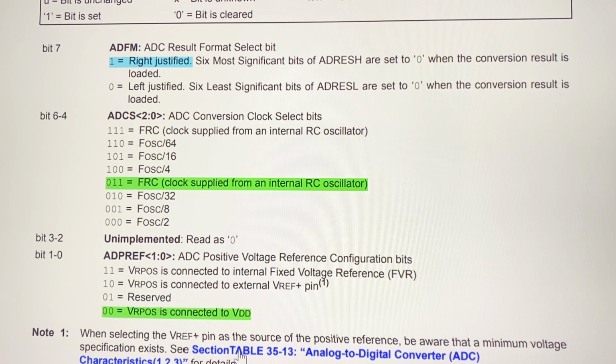But if you are working in an instrumentation experiment, and your sensor requires an external voltage which is different, then you have to select 1, 0. There are also internal fixed reference voltages. You can select it with number 3, but in this case it'll go to VDD. So our range for the trim pot will be from 0 to 5 volts.